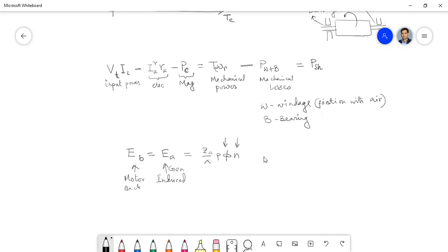In the case of a shunt motor, you are always giving the flux, because the supply voltage is always connected across the field. That means you always have the full flux. So without the armature current also, you will get the back EMF generated. These are all constants, isn't it? The same expression you can write like this. So you need the flux and you need the speed.